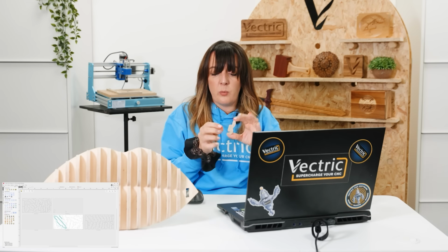We also need to think about the larger areas of our board where we may have the 3 tab panels. Because we're only working with tabs that are 0.36 wide, will they hold with a very, very large piece? So I want to check the stability of that.